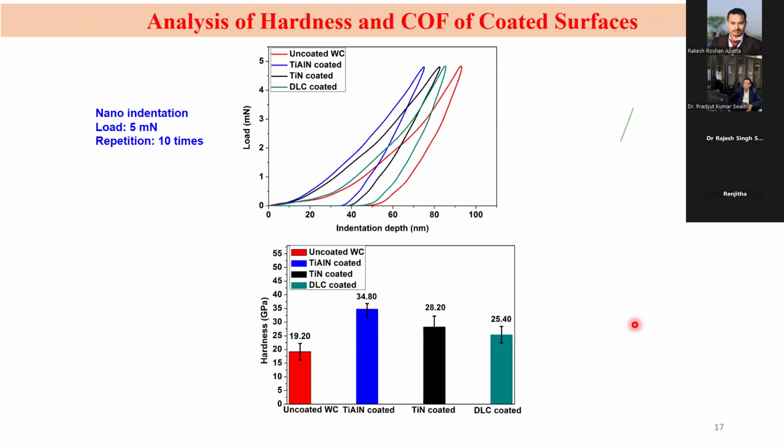So we choose two materials, two frontline materials. One is Ti6Al4V, that is grade 5 for the aerospace grade. So here the combination is titanium and aluminum and vanadium also. And next we choose P20 steel. So one is a ferrous material, one is a non-ferrous material. So we started doing this kind of thing.